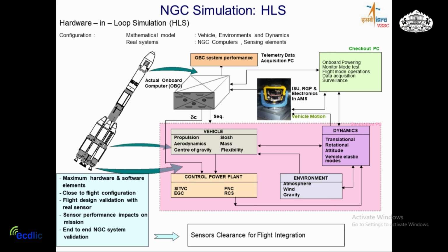That is difficult because till now the simulation computer was able to give rotations in a mathematical form, but when you have the actual sensors, you need something physical which moves to rotate the gyroscopes. So for that we have an angular motion simulator like this, which is a 3-axis motion simulator on which the navigation sensors are mounted, and this is interfaced to the simulation computer, and so the whole cycle is repeated like that.